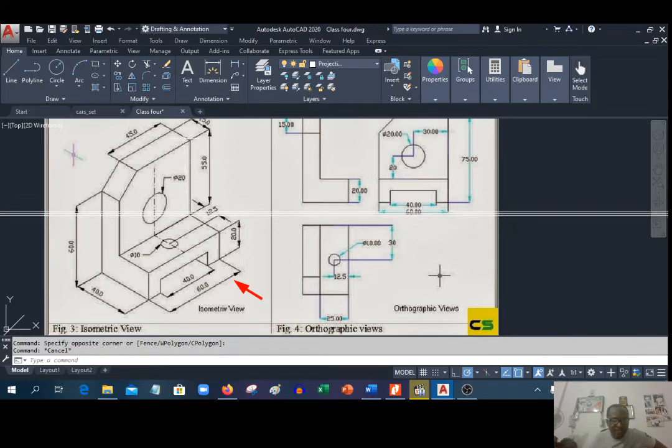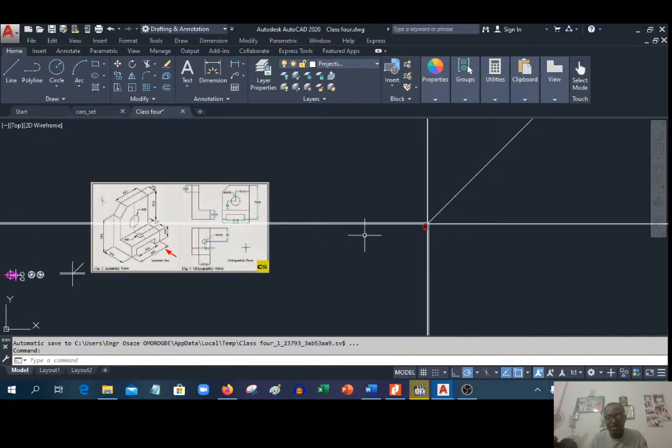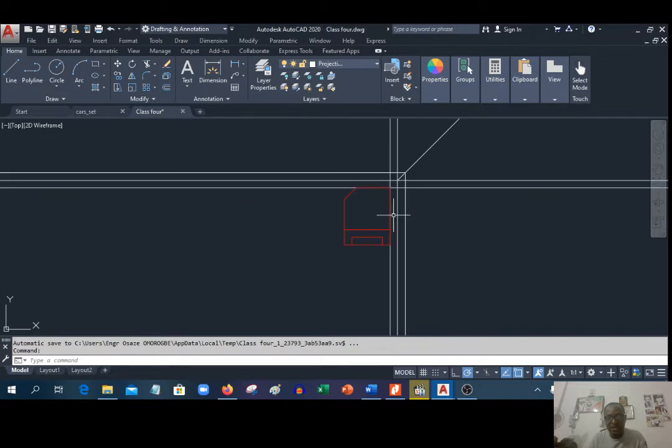The 55, right? So the midpoint of this line 55 would have been okay for us to use to get this. But the way it is, let's come back to our drawing and see if we can get it by mainly looking at it, because the hole in the flat base is given, but we cannot see that from the direction of projection we're working on. So let's come back and try and locate it.